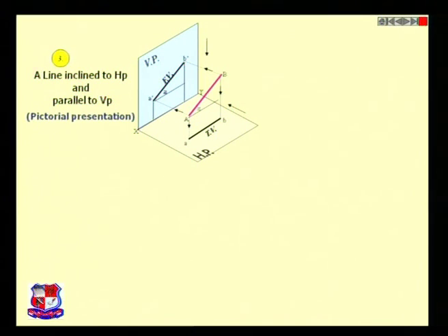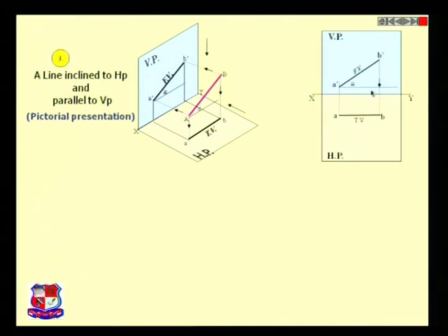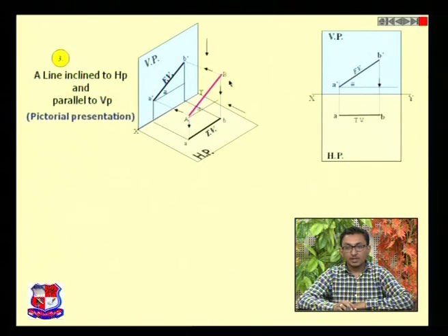Like this, we have taken the projections, light projections, till the XY line, and we have taken it to the small a b. Its orthographic representation, as you can see over here, is very much clear. This red is our line, the original line is our red line. If we trace the projections of this red line from the front view like this, we are retaining the exact angle as well as the length. We are retaining both these things. But if we are seeing it from the top view, as you can see in the orthographic projection, the top view length would be shortened.